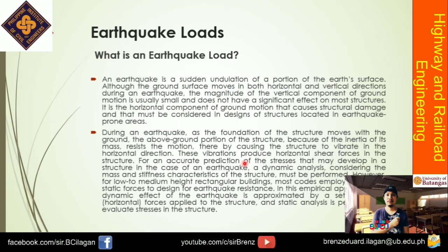For an accurate prediction of the stresses that may be developed in a structure, in the case of an earthquake, a dynamic analysis considering the mass and stiffness characteristic of the structure must be performed. However, for low to medium height rectangular buildings, most codes employ equivalent static forces to design for earthquake resistance. In this empirical approach, the dynamic effect of the earthquake is approximated by a set of lateral forces applied to the structure, and static analysis is performed to evaluate stresses in the structure.